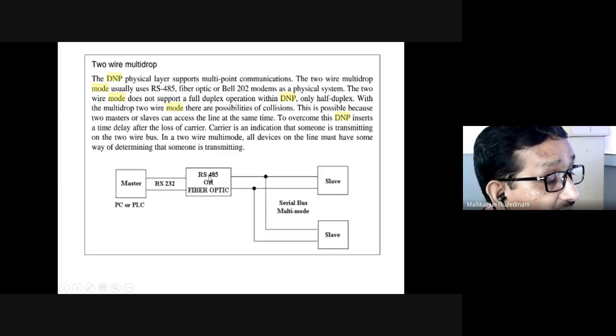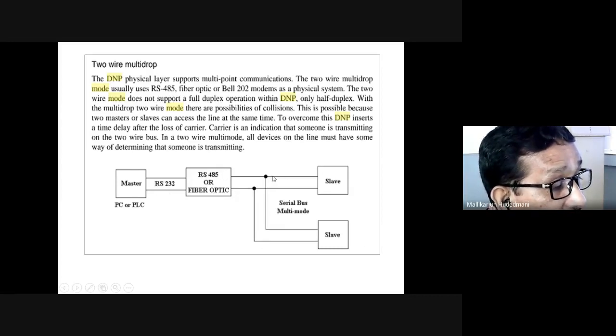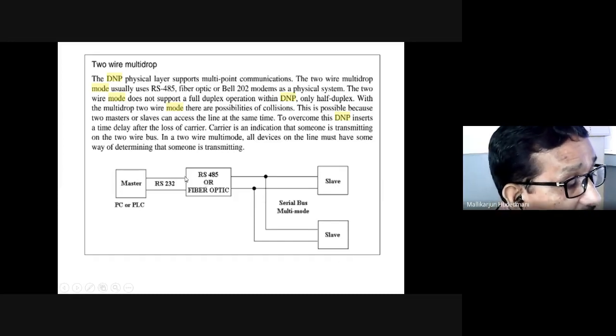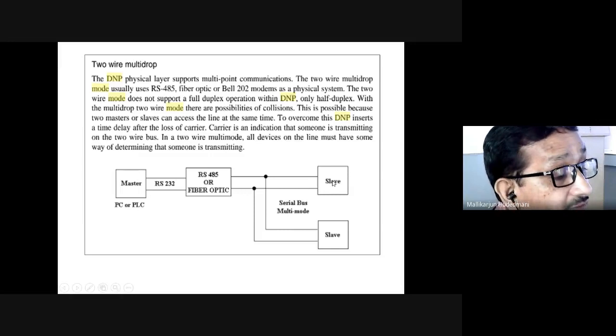The RS-485 converter takes the data serially, as two-wire data. It will make a two-wire multi-point. Then these two wires will communicate to the slave as well. Before they get communicated, it will send the information called an identification tag for the device number,